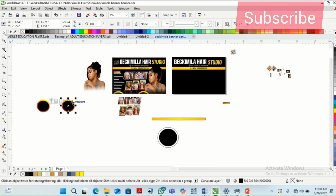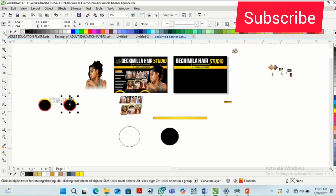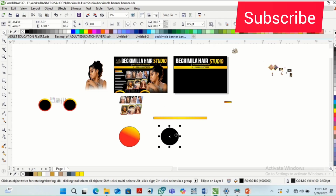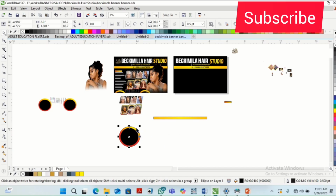Now, I already have this fill color here. Instead of using my interactive fill tool to redo this work, what I'm just going to do is hold down the Control key, then drag and select copy fill here. You can see that I have exactly that same fill in this place. Now I'm going to place the black on it. So I've made the exact shape that I wanted.